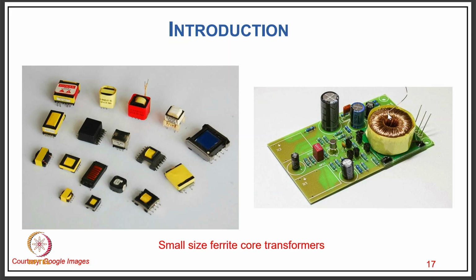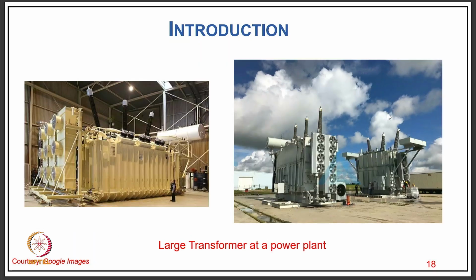DC isolated supplies. A typical example is the computer power supply, where you need a power supply for the cooling fan, for the motors of the floppy disk drive and hard disk drive, and for your processor. All these DC supplies are isolated and of different voltages. So you have several secondaries in the transformer which give you different voltages, where you keep different numbers of turns.